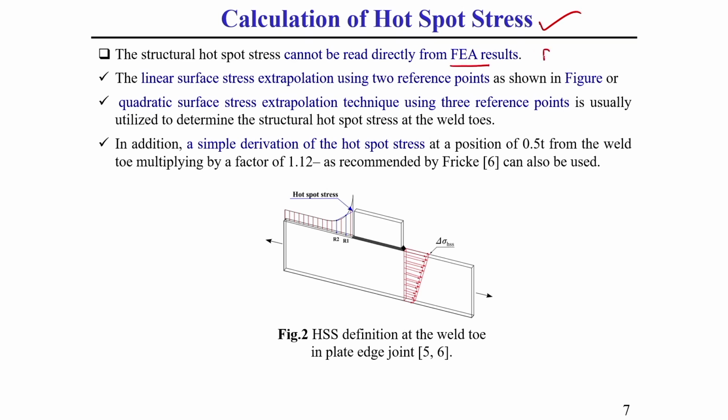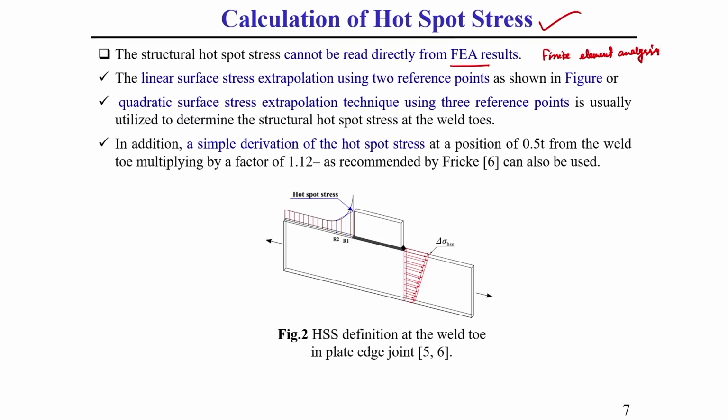FEA means finite element analysis. Okay. But what happens, from FEA analysis we cannot directly predict this hot spot stress, this you should keep in mind. For predicting the hot spot stress using FEA analysis, we cannot measure this hot spot stress directly from there. For that, some extrapolation techniques are required. What are those things, in details I will discuss.